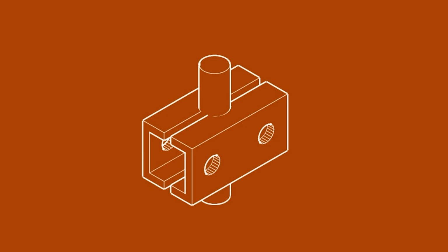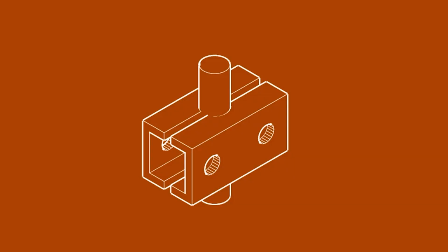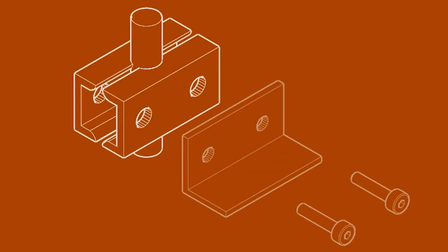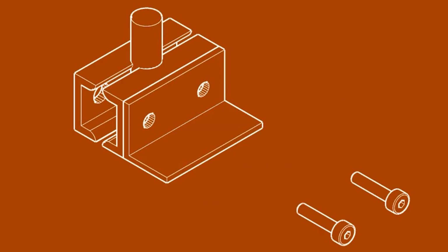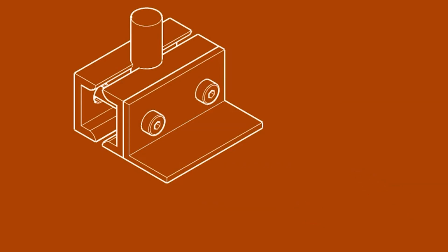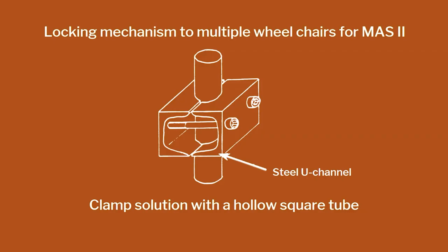Can I not use standard parts? So they said, yes, we can. We have channel sections. We can buy sections that look like this. So can I take two of those and put them back to back, hold it properly, take a thin material out in the middle, and then make the hole, and now it's ready for working, right? And now I have reduced the number of parts and also standardized. The more you standardize, the better, because if I am producing that part in millions, my quality is going to be better than if you are making 3. So therefore, we should take advantage wherever possible.